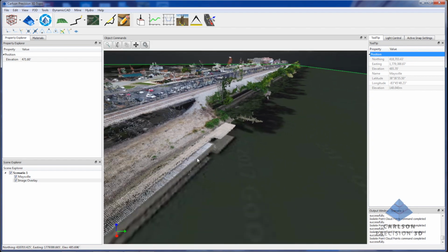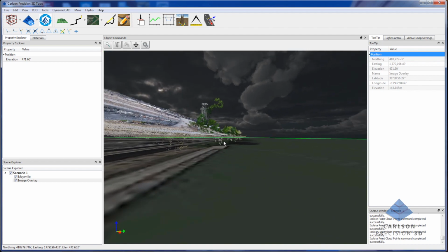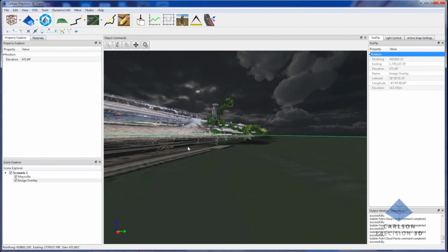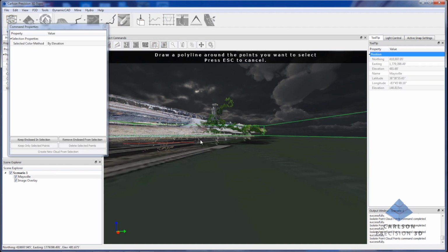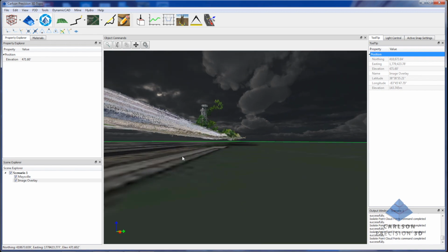And also, there's a lot of times where you'll end up with data with points that are just underneath of the point cloud, which gives a lot of the bare earth algorithms a lot of grief and so forth. And so we could certainly use the same crop tool underneath of this surface as well to really clean that up. So here I'm just going to quickly get rid of these stragglers that are down below and clean that up.